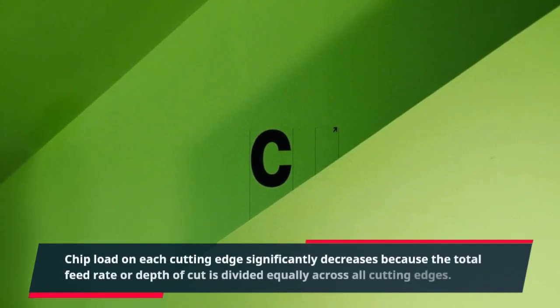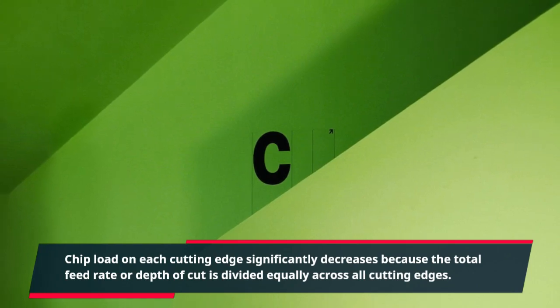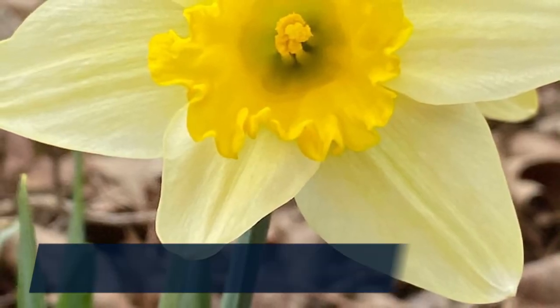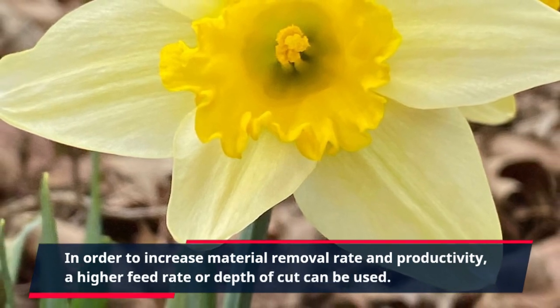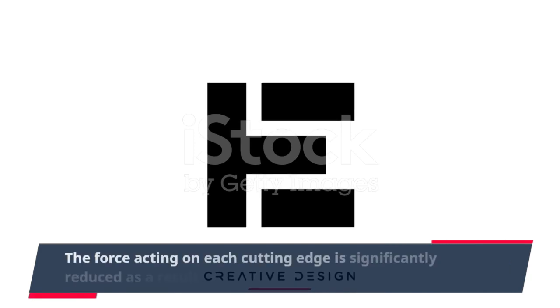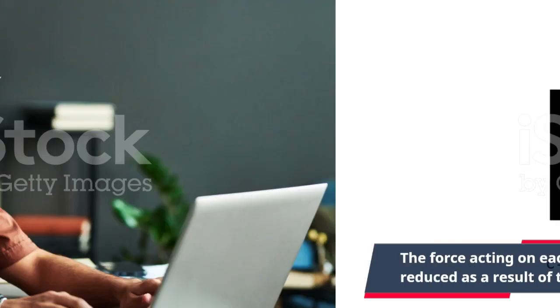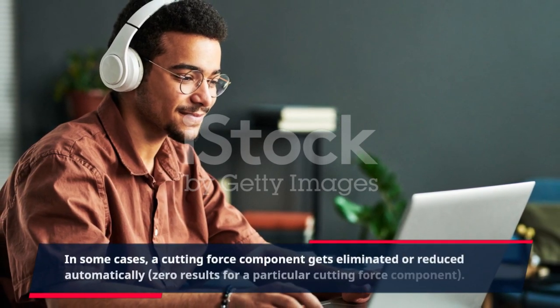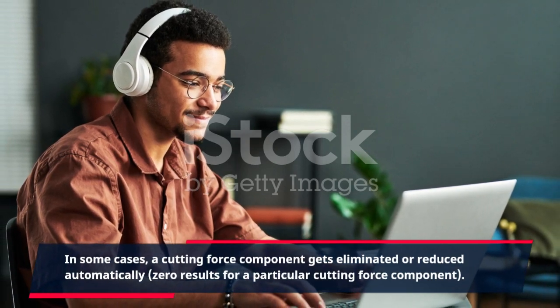Chip load on each cutting edge significantly decreases because the total feed rate or depth of cut is divided equally across all cutting edges. In order to increase material removal rate and productivity, a higher feed rate or depth of cut can be used. The force acting on each cutting edge is significantly reduced as a result of the distribution of chip load. In some cases, a cutting force component gets eliminated or reduced automatically, resulting in 0 for a particular cutting force component.